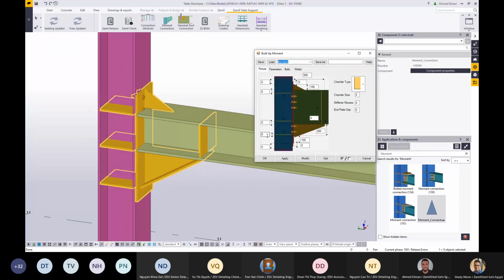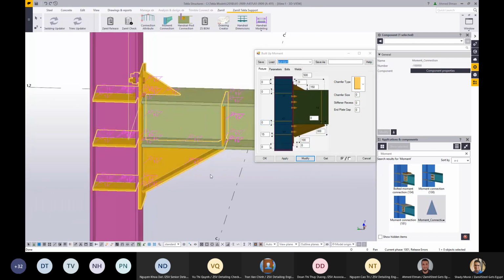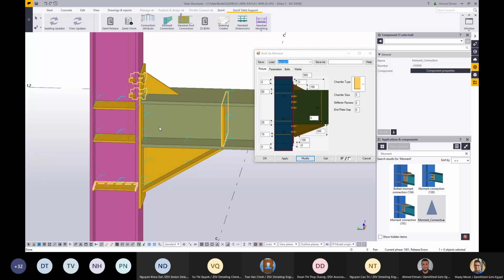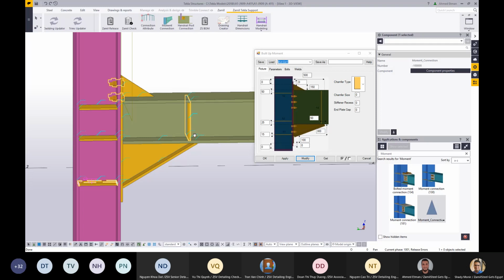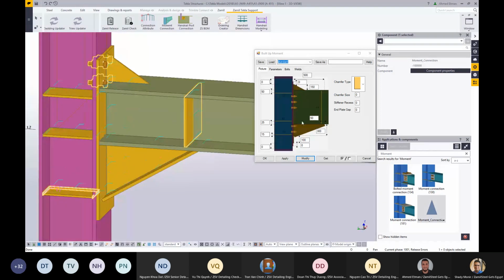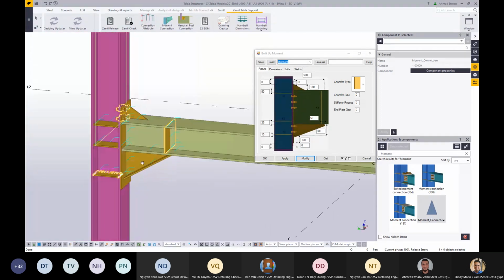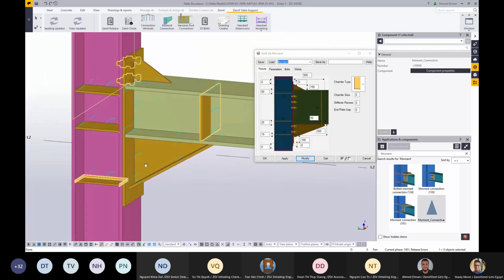Also, you can shift all these stiffeners. You can modify their position by modifying this value. If I insert a shifting here of 15 and a shifting here, for example, 25, and a shifting for S1, for example, to be 50. And a shifting for S4, for example, I'm going to shift it 50 also. You can shift this value with either a positive or negative value. You can modify the position of these stiffeners.